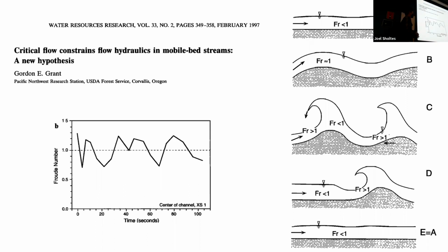This gets into geomorphology or the shape of rivers. But if we think of, for like a mountain snowmelt fed river, every year is going to get that kind of flood. It's going to change year to year. But that flood event is slowly moving and arranging sediments and establishing a width and a slope. And if it's a steep enough kind of system with a certain kind of sediment supply, he argues that this is going to be the condition that develops.